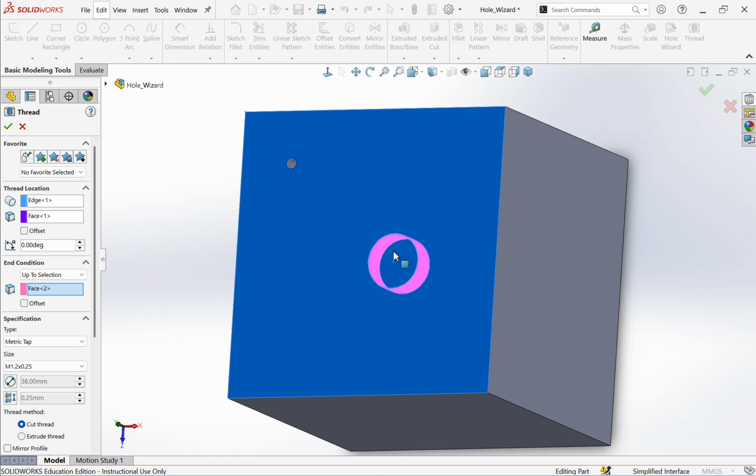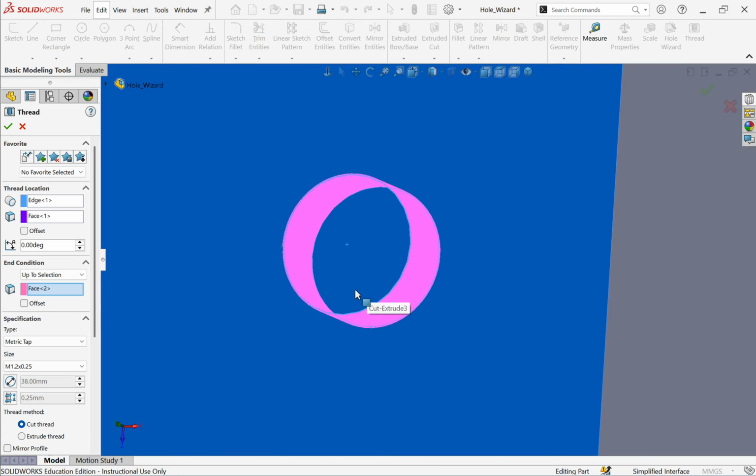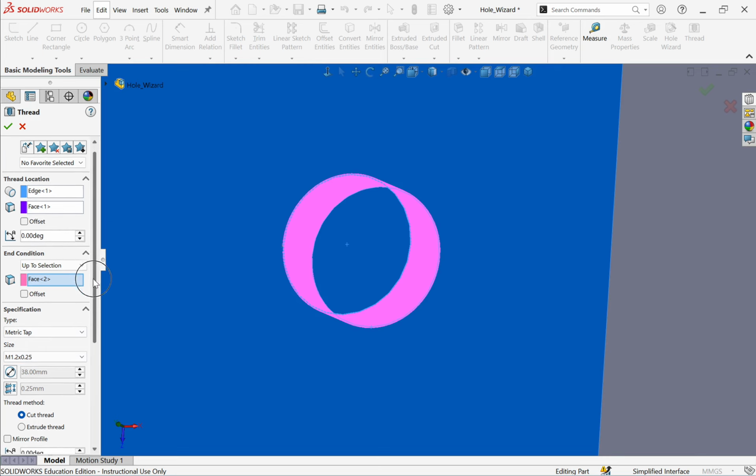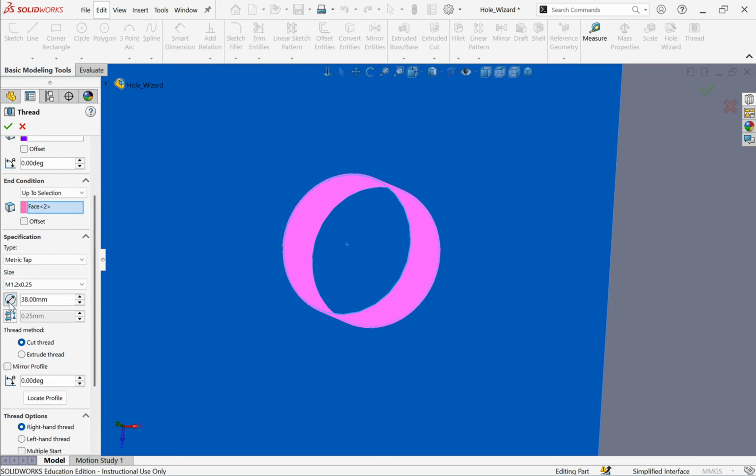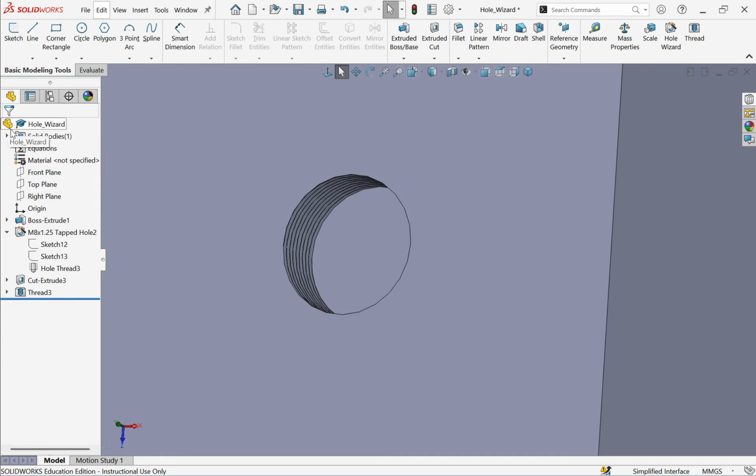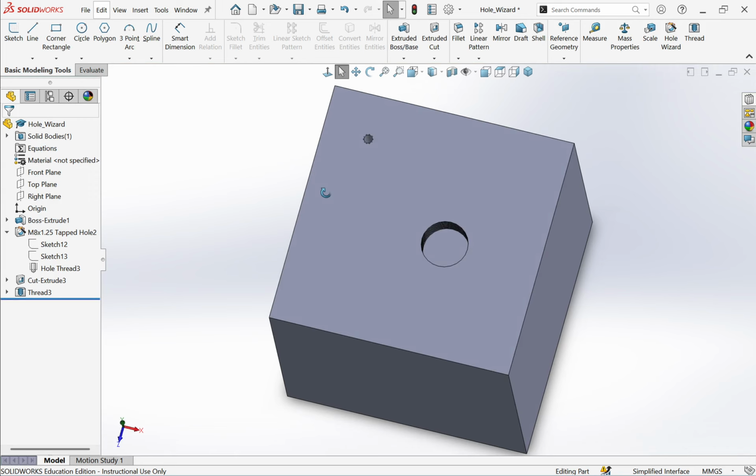When you see that preview, you know that it's probably going to create that. The last thing you need to do is, if I hover over this, I think it says override diameter. And if I hover over this, override pitch, thread pitch, same thing. So to press that button, hit 2. That's my thread pitch now with diameter 2, and you can visually see how it changes. You can play around with that to get a better idea what thread pitch means. Say okay, and there you go, done. Make sure to save your part as always. That's it.